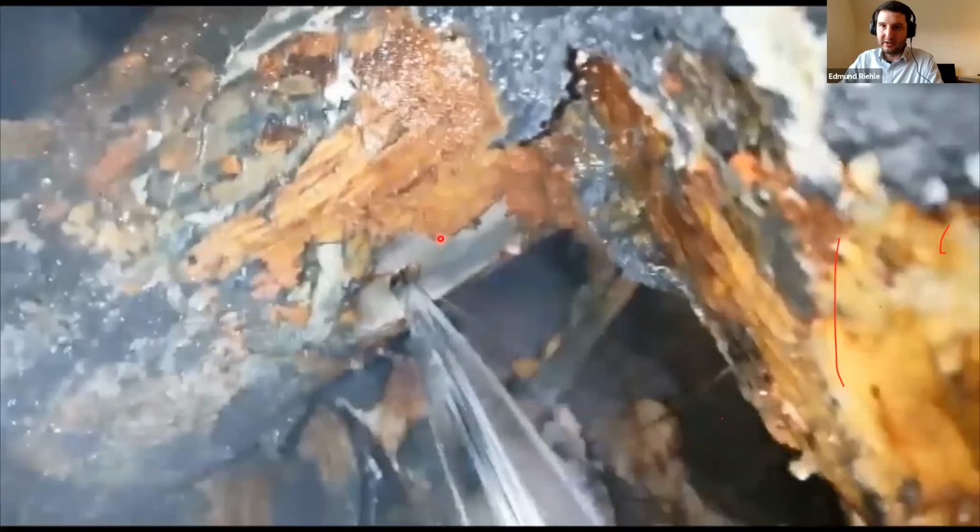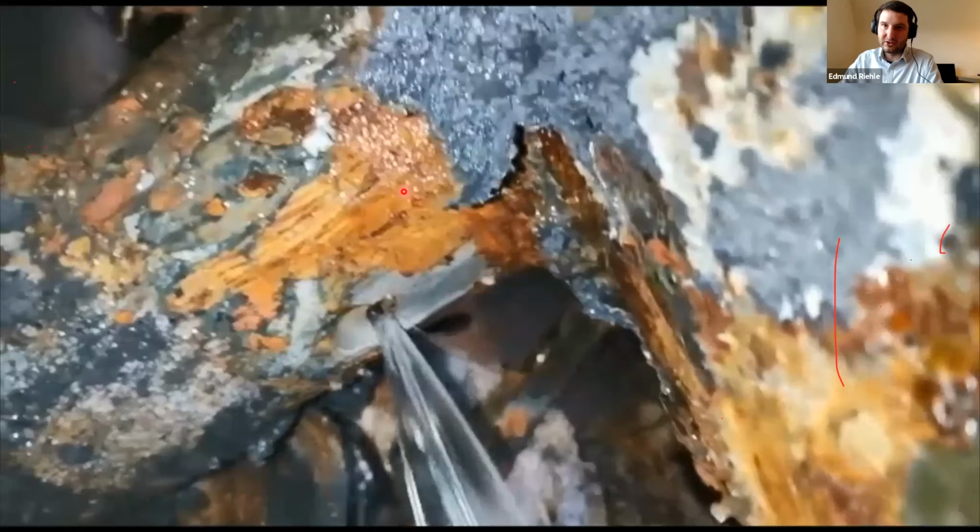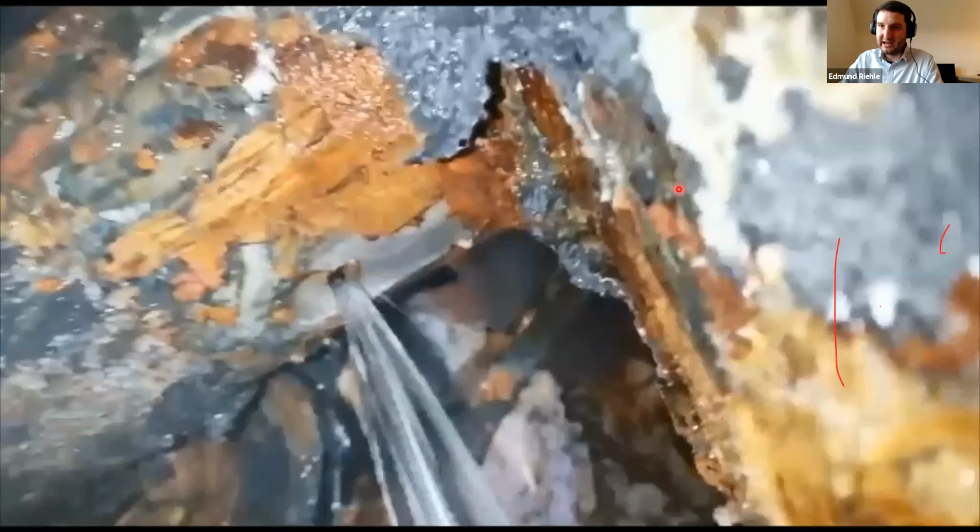And that is the leak in the end when they excavated it and cut the insulation. So it was on a joint or like a service connection where they had it on the main pipe, and we inserted it in the main pipe, and the leak sound really distributed along the pipe, and we could hear it a long distance before and even after the leak. And therefore, you could not really identify it very, very precisely.